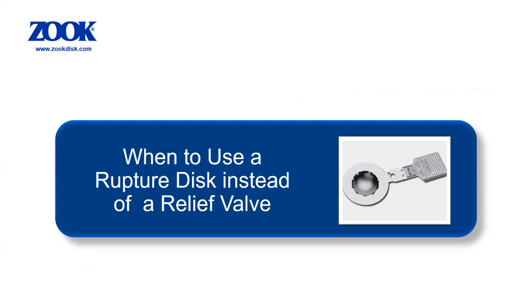Comparatively speaking, rupture discs are very inexpensive compared to valves which have large housing and integral mechanicals, especially in larger sizes or when exotic materials of construction are required. Second is leak rate. Valves by their nature can leak, which can be a problem in some services. Rupture discs, however, are visually leak tight. They are basically a solid barrier with leak rates at the molecular level. The disc is very fast acting and unlike a relief valve, does not require a change of direction for flow to take place. There are no moving parts in the disc, so the reliability is high. There is no way to adjust the disc setting, which makes it tamper-proof also.